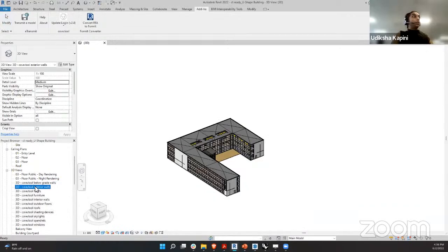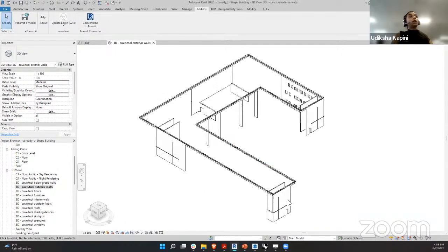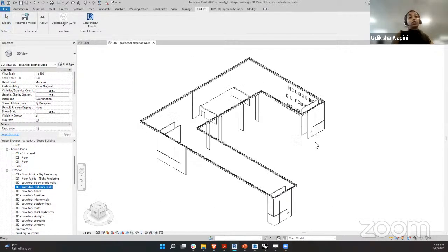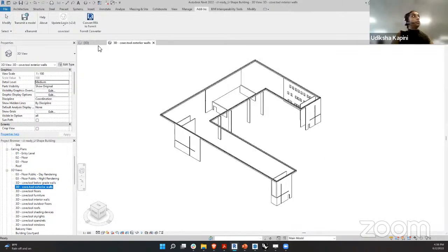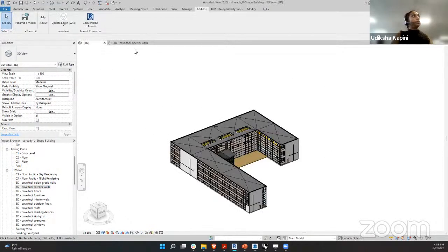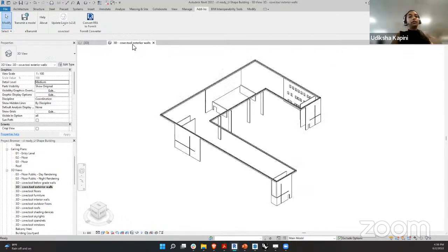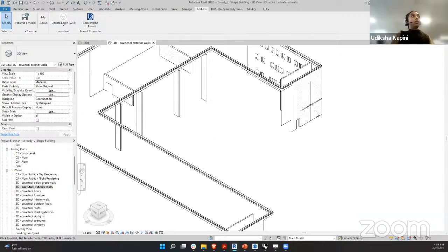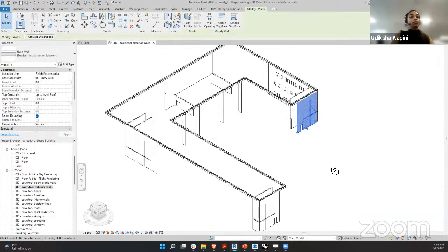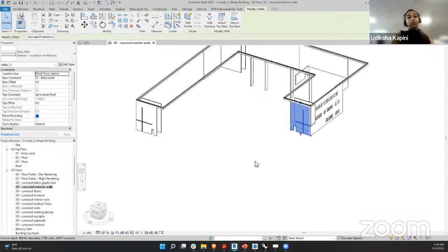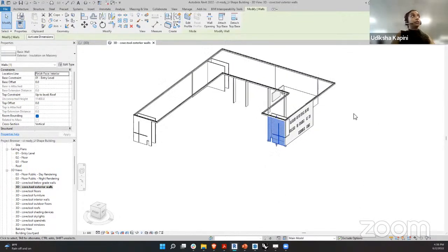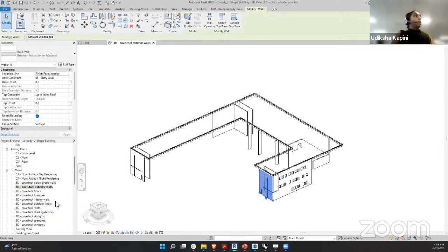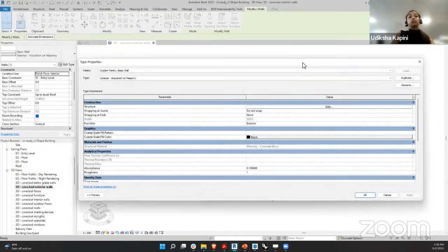And these views are basically filtering based on object properties, what is relevant for each of them. For example, all your exterior walls are now filtered from this overall 3D view into this view. And they're basically on visibility, whatever is visible in these 11 3D views is what's going to get exported. And like I said, these are based on properties of the object type.